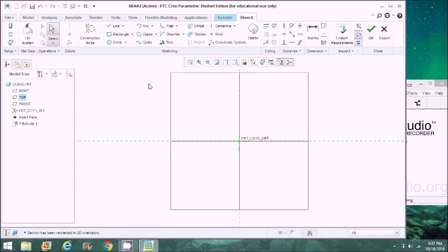First we're going to make the circle shape, and here's the circle tool. If you click that once, come to the center and click once there, and then drag your cursor out, you create this circle. If you click again, it will stay in one place.